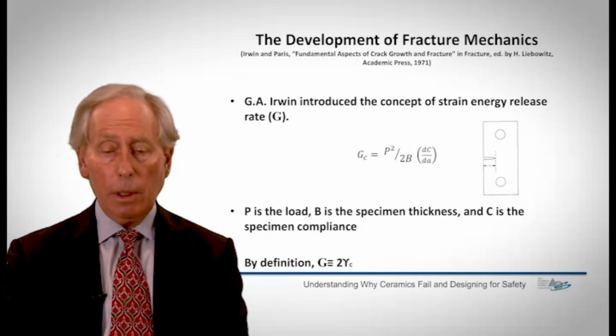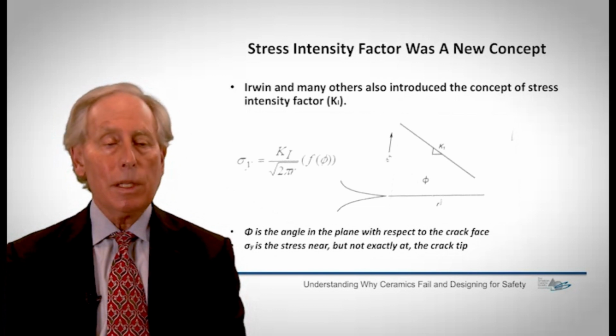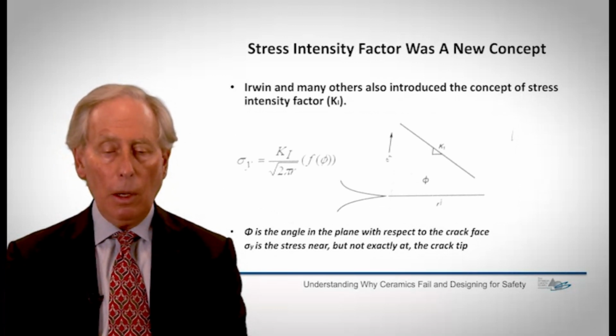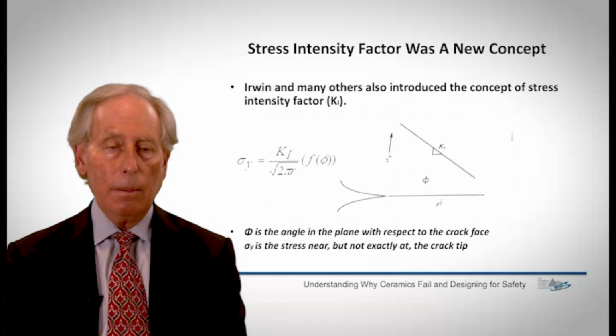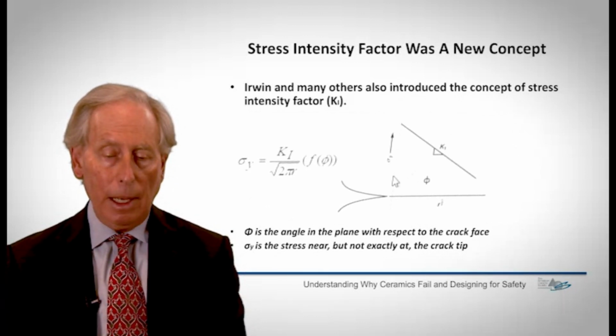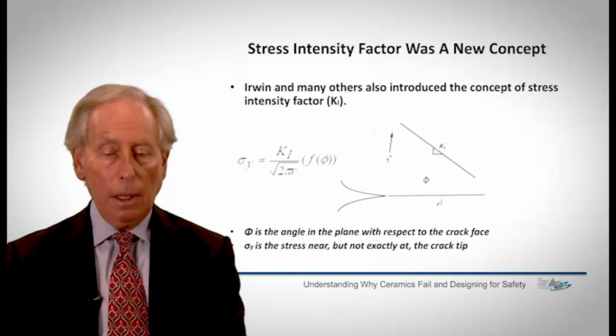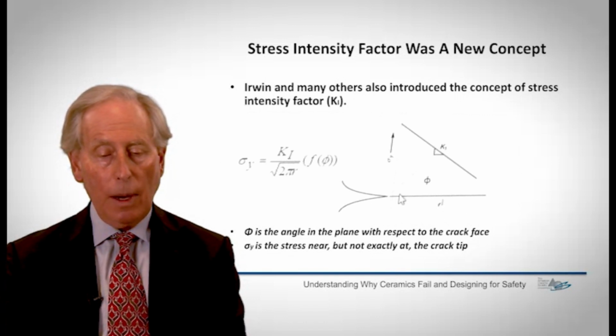Some of you have heard of the term stress intensity factor, and I'll just take a moment to define what that is. If I apply a stress to a specimen in some load, what I call far field, in other words, I pull on the specimen, I apply a stress in some fashion, then the stress near the crack tip, and I'll show in a moment it's not right at the crack tip but very close to it, is related to what is called a stress intensity factor, and that stress decreases with distance away from the crack itself.